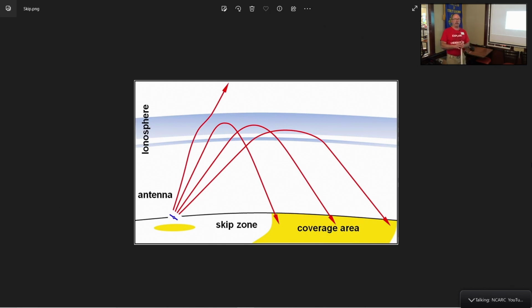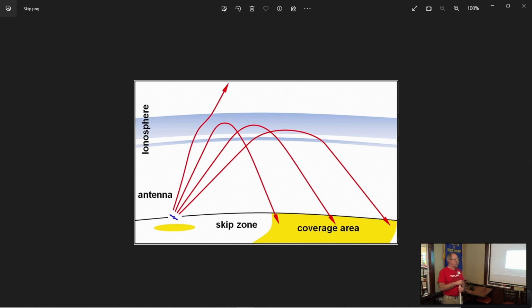This is before we even get into the issue of things like mountains, which we tend to have just west of here, which RF doesn't go through very far. So if you put an antenna up vertically, and we're going to talk about an HF antenna here, either a big vertical dipole or something elevated with elevated radials, or something sitting on the ground with ground radials going out, your RF is going to go up at an angle. It's not going to go straight up because of the ground. It is going to go up a bit, but at an angle, and it's going to encounter the ionosphere.